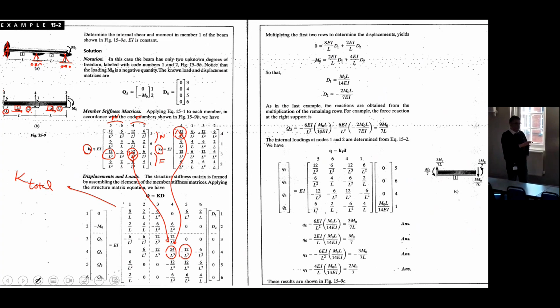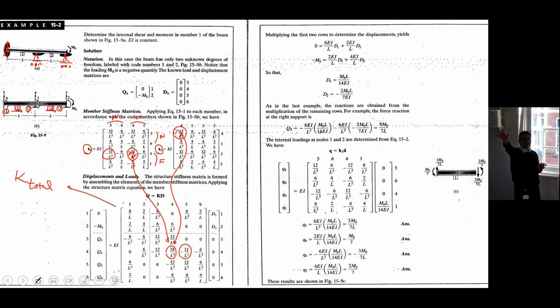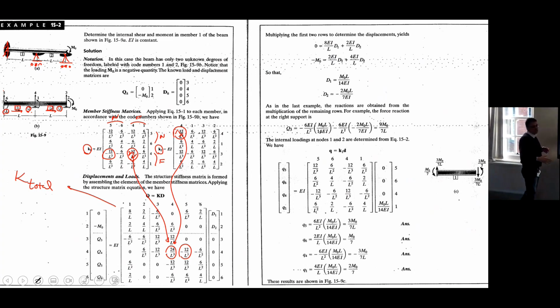That cell 4 by 4 receives 1 and 2 numbers together, they add up, making 24 instead of 12, right? It makes sense in a physical sense because degree of freedom number 4 is this one. Transversal deformation, vertical deformation along the y-axis.